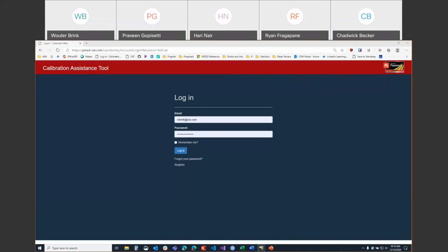So if you use, say, CBR for your subgrades and now for the calibration sections you use R value or any of these other items, that's building in an extra complexity that from a design aspect you're not going to use. So that's why you want to make sure that everything's compatible and reflects your agency specific practices.